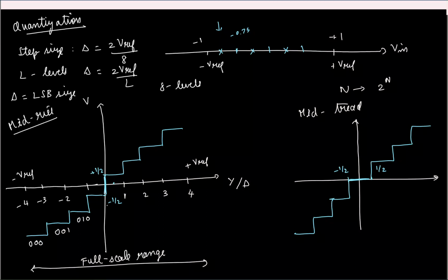Sampling is linear, but it is not time-invariant. No, sampling doesn't involve convolution in the time domain. It convolves in the frequency domain, but we are looking at operations in the time domain, right? So sampling is a linear operation. What if we take two analog signals, the first with magnitude 0.2 and another with magnitude 1.2? No, I'm not talking about quantization, it's sampling alone. This sampling is linear, right?